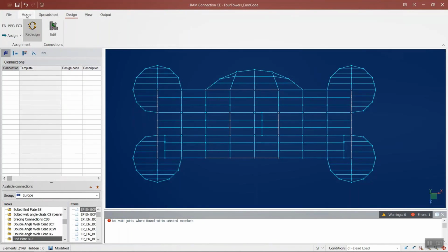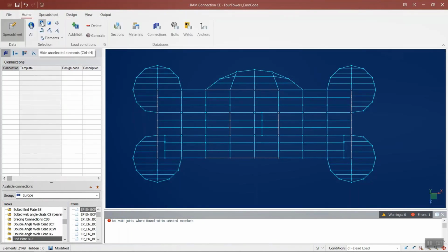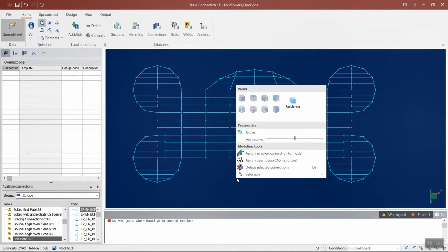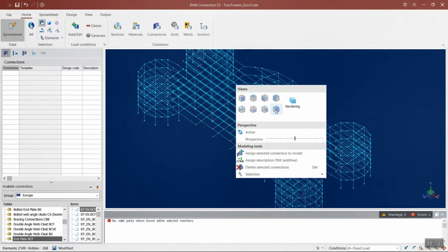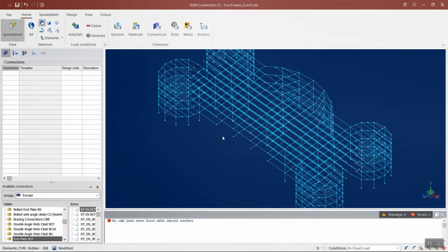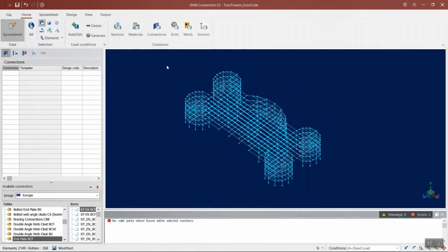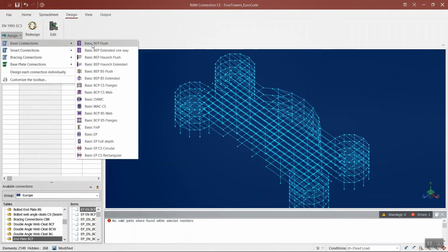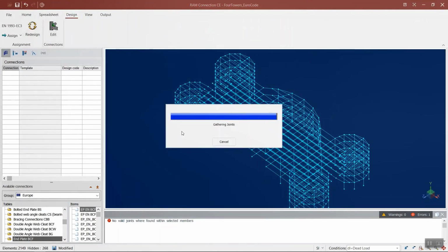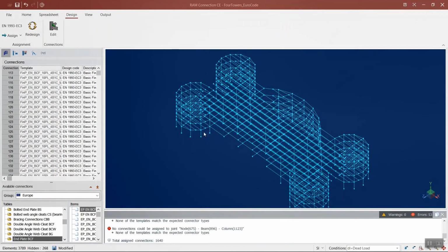Okay, so now I'm selecting only the gravity members, which is made of hundreds of columns and beams. Elevation view and then the isometric view. Notice that I removed all the lateral members from this model for better visibility. And now all we are viewing is gravity members, which is the majority of our building. And I'm just assigning a simple fin plate connection for all these gravity members,